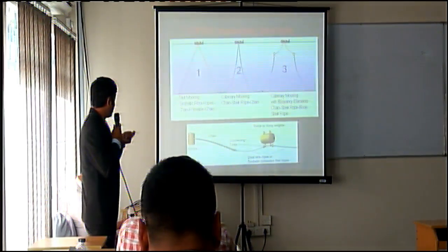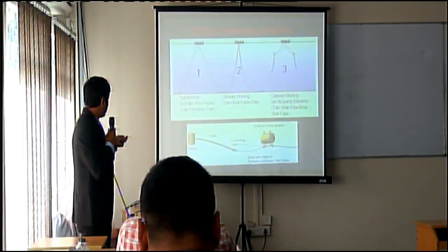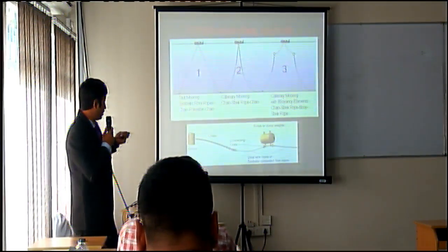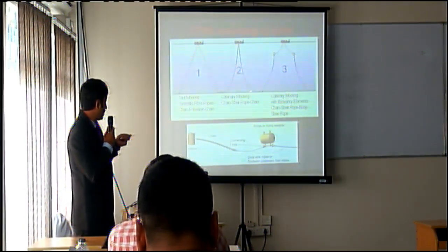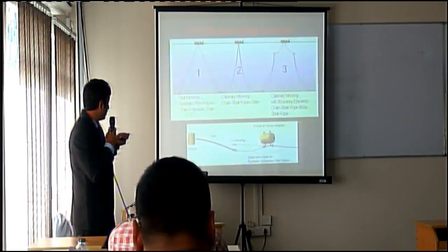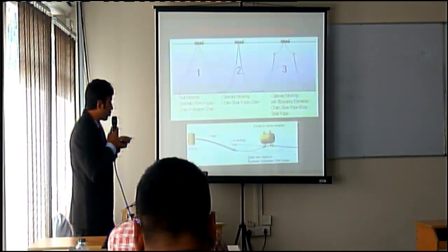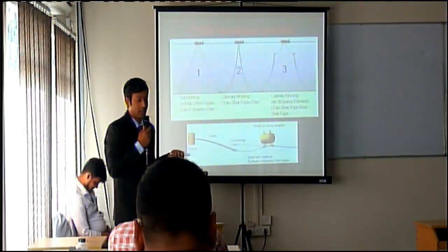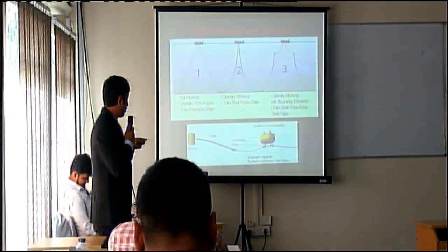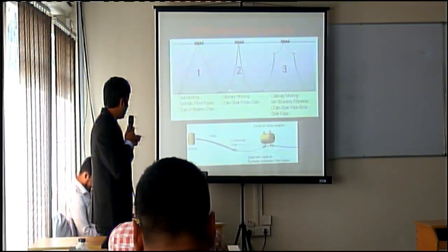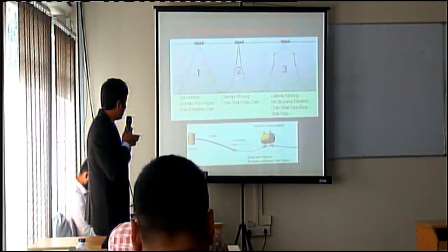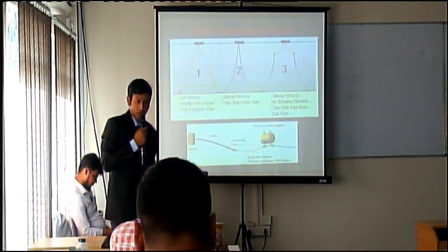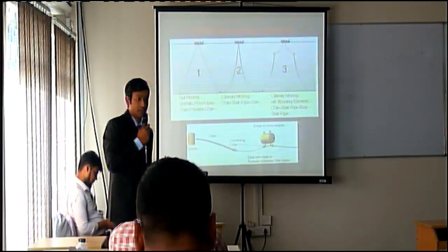So yeah, we're talking about these three. Though I haven't done research on which one is better here, as you know, chain is more prone to fatigue. Not the steel wire rope, it is not that much. So if you can use lesser chain and more wire rope, it will be better for your design of the mooring line. Also, it will give you lighter weight.